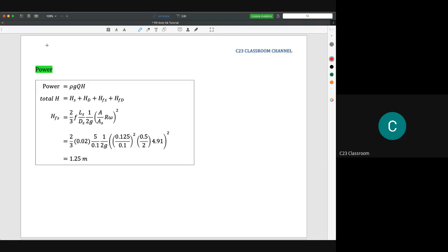Because in a piston, they move in 3 major situations, which are the beginning, the middle, and the end of the stroke. So these 3 points will give us different values in terms of angle, and then we will have 3 different values. In this situation, because we only want one value to be substituted in the equation, you are allowed to use the average value of the friction.